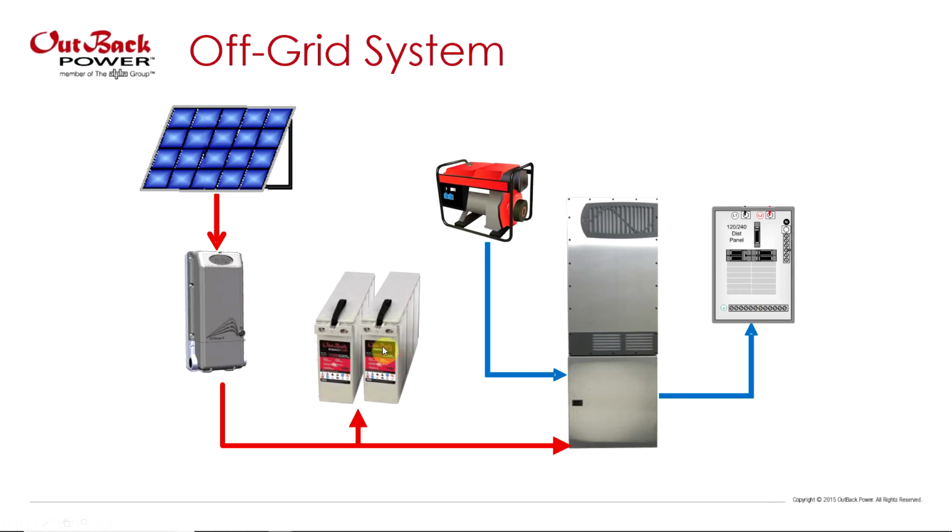Remember, the PV array has to go through lots of conductors, your charge controller, maybe into your batteries and back out of your batteries, possibly, and then to your inverter. So that's kind of the worst case, your 81%. But when you're dealing with battery efficiency, the battery is really just output through your inverter to your loads. So when we size our batteries, we're just going to be using our inverter efficiency, because that's the normal path. Okay.